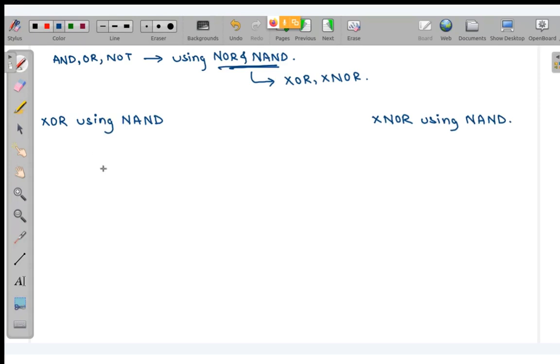So look very carefully at how the structure will be. You might be very tempted to draw like this. So I am drawing a rough diagram. What is XOR? It is A XOR B. This is in our form only. We have seen how to construct AB plus CD, so it is kind of that only. I can construct it if I am able to construct A complement. So this is A, this will be A complement.